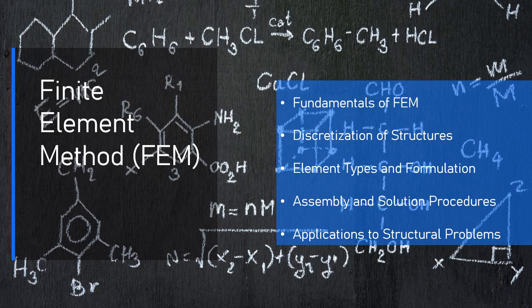The internal force vector F_int can be derived by multiplying the element stiffness matrix with the calculated displacements. F_int equals k_e u_e, where k_e is the stiffness matrix for an element and u_e is the displacement vector for that element. For each element, this can give the reaction forces at the nodes, which can then be used to assess the structural performance under the applied loads.